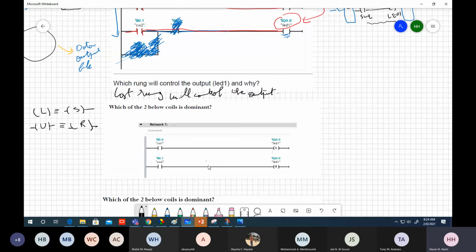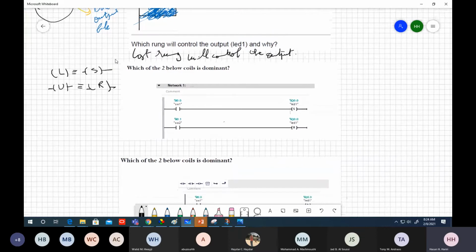So it's exactly the same exercise, but instead of just putting energize if on, we are putting set and reset instructions. Let's take the fourth scenario. Okay, so we have four scenarios, but here you need to be aware that it's not only switches, right? Because it should save the state. Here it's set and reset.